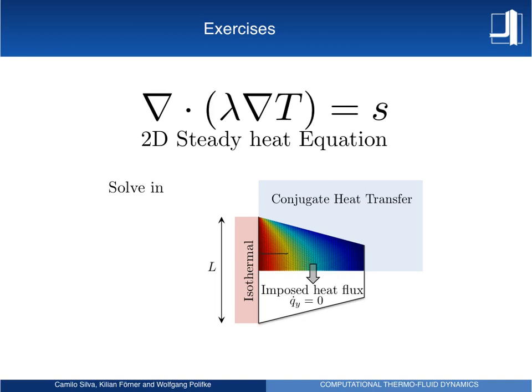So you have to be capable of saying, I'm getting results, but they are garbage because they are not actually doing what they are supposed to do. Sometimes you have to have this intuition to evaluate how good the results are. And the basic thing you do to evaluate the goodness of a result is at least to see that the boundary conditions are satisfied. This is the first thing you have to do. That is a quick check. So you check, yes, here the temperature is what I impose, here the normal boundary condition is clear because the iso lines are normal to the surface.